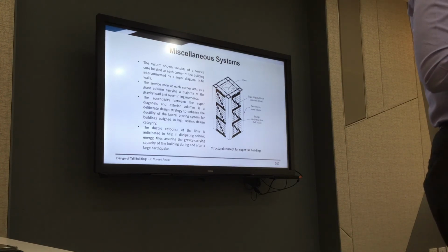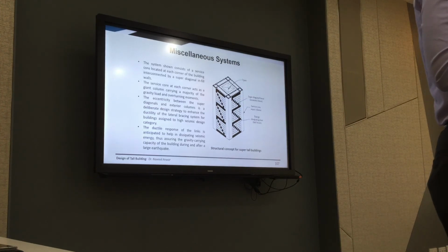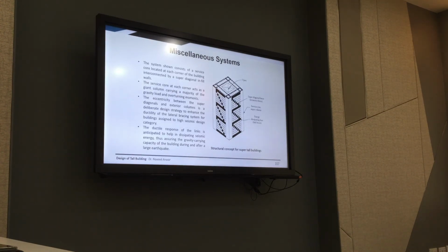By knowing that now, we can retrieve the deformation pattern by using the outrigger, and also can reduce the bending moments. Okay. Good. Yes. The main concept is that the bending moment is converted into axial force, and the pattern of design for earthquake or wind is almost opposite because gravity and lateral loads are two different factors involved.